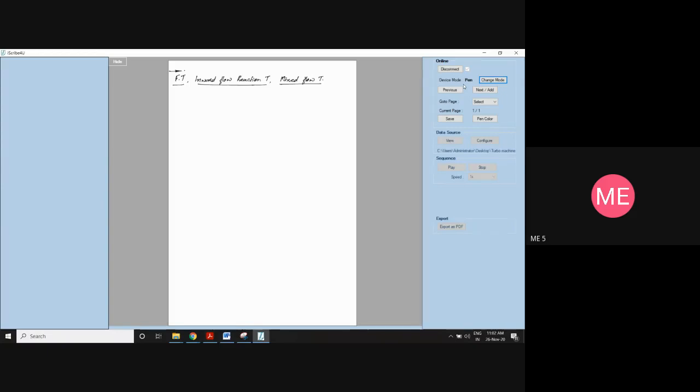Here, instead of giving directly the Francis turbine, he has given inward flow reaction turbine. That means it is a Francis turbine only, which develops a power P of 12,365 kilowatts and uses a discharge Q of 12 meter cube per second of water when the head is 116 meters. That is head. The runner has a diameter of 1.5 meter. I don't know whether it is inner or outer, so I'll just write D. Based on the value, I'll write 1 or 2. If it is higher, I'll write 1. If it is lesser, I'll write 2. Just I'll write 2 for the time being.